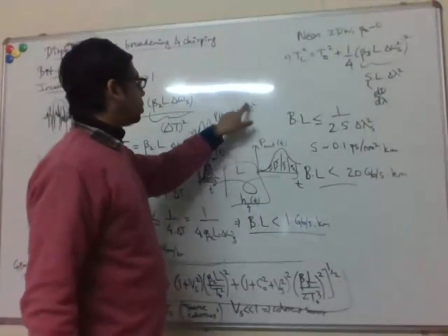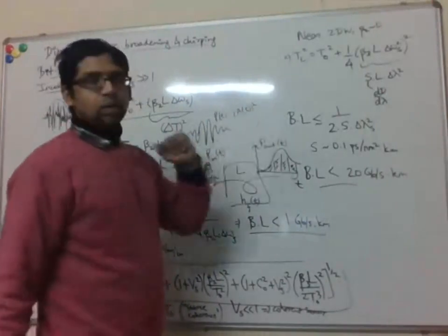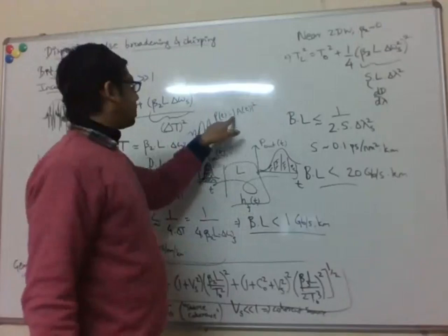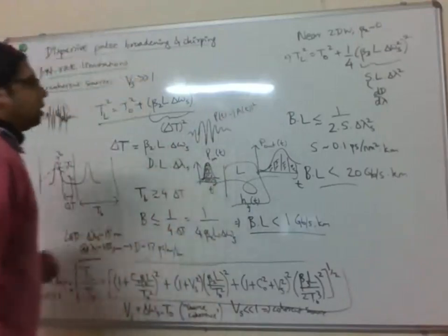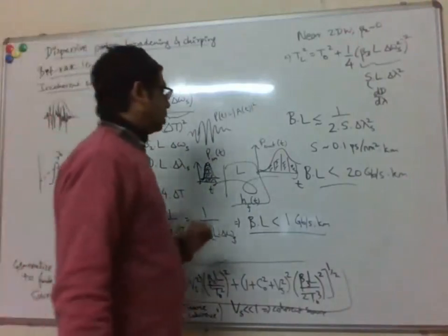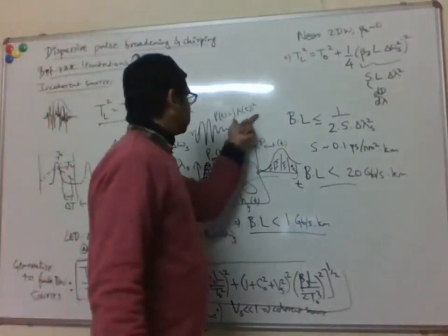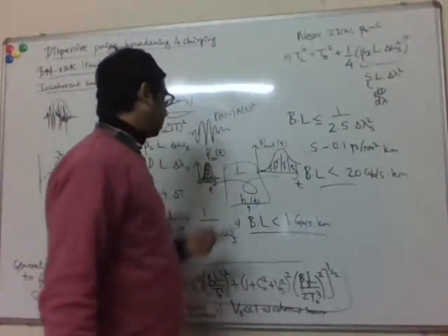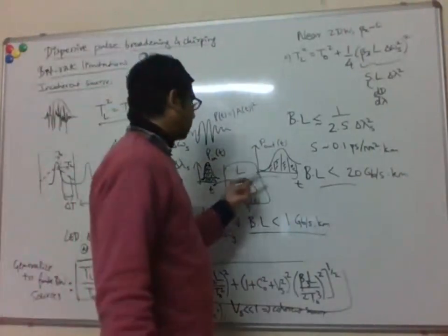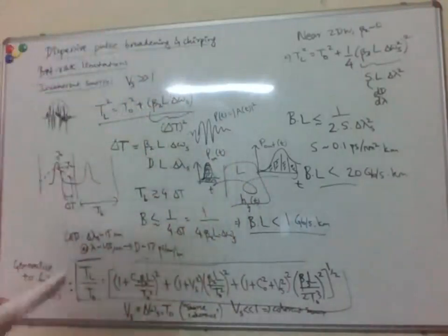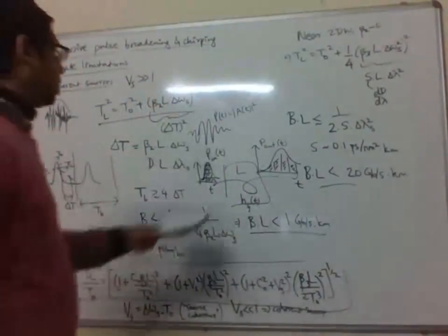We know how to calculate A of t on propagation, but since the power is the mod of A squared, for coherent sources we have to use the pulse broadening formula, and we can't define a transfer function like this. But for incoherent sources, we can.